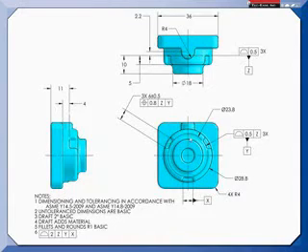And then we have these 3 widths here, but we're going to have the tooth that goes into this one a nice fit to drive it, and that's going to be our datum feature X. So these are functional because they constrain the degrees of freedom in the machining process.